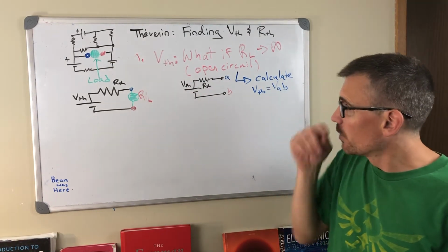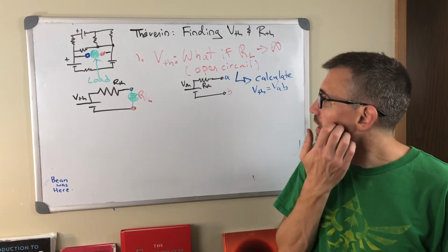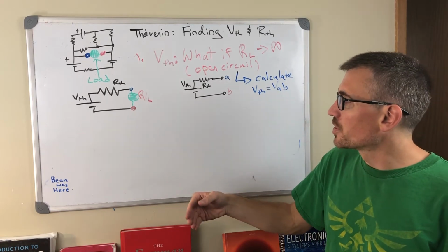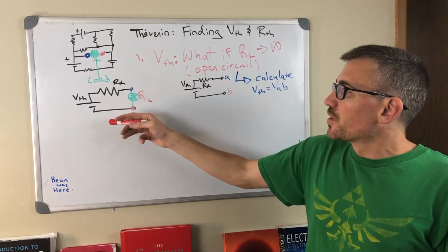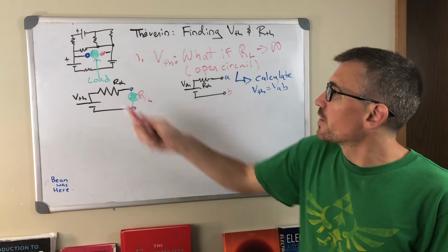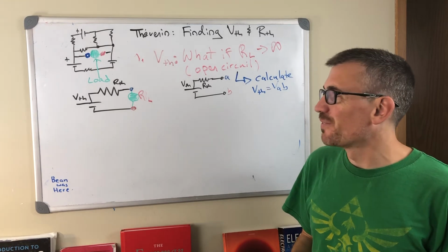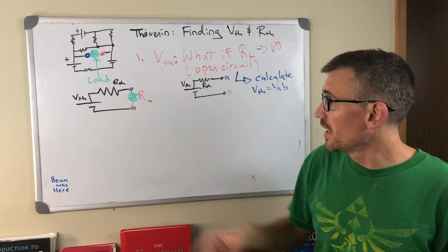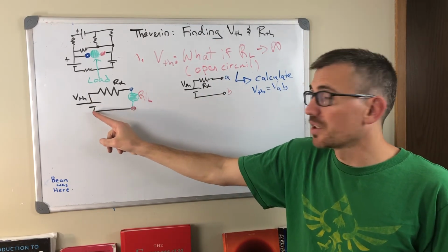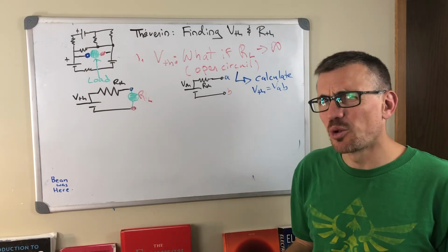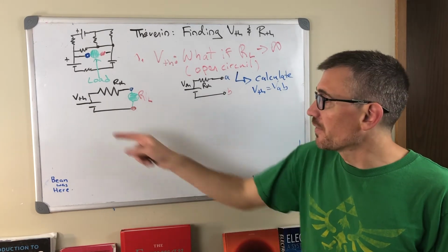What's option 2? Well, another thing we can do is exploit linearity. Remember what linearity says. It says that if I scale up the voltage sources by the same factor, a factor of 2, all the currents are going to double. If I scale the voltage sources down, similarly, by the same amount. So we can divide every voltage source, whatever it is, by 2, and 2, and 2 again, 2 to the 50, right? We can scale them down to 0. If I scale all the voltages down by the same amount all the way down to 0, I've effectively replaced this voltage with a 0 volt battery. What's a 0 volt battery? Remember, this is the ideal voltage source here, so it maintains a fixed potential difference of 0 volts across it.